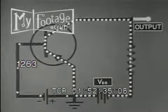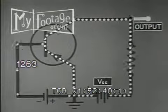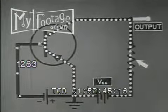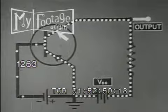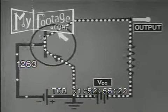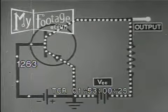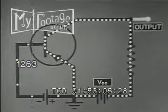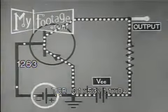In the on state, when the voltage at the collector junction is 0, the collector current depends only on the collector battery voltage and the load resistance. The collector is in a state of saturation. It can draw no more current, no matter what the emitter may do. Under these conditions, practically no power is lost in the transistor. However, the response of the circuit shown here may be undesirably slow.